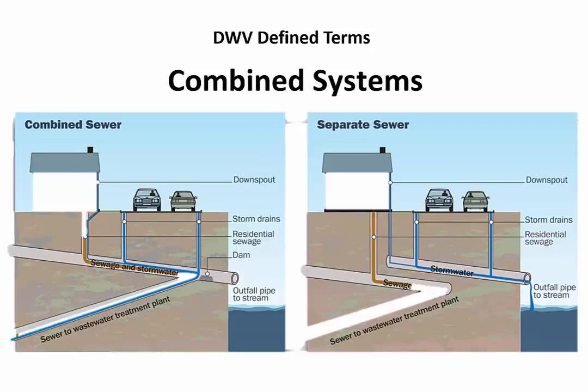Combined systems convey both sewage and stormwater and can lead to widespread contamination when storm flows are heavy. Most areas attempt to maintain separate systems to avoid environmental pollution and unnecessary additional treatment of stormwater. When permitted, combined building sewers are sized in conjunction with Table 24.10.9 and in conjunction with Article 24.10.5.